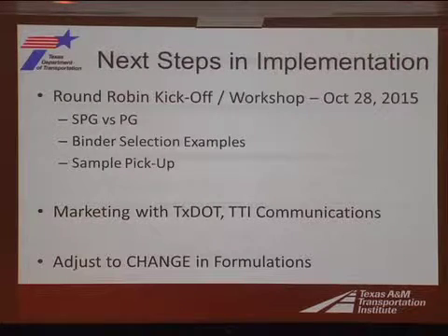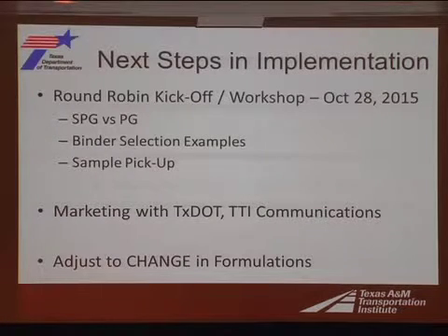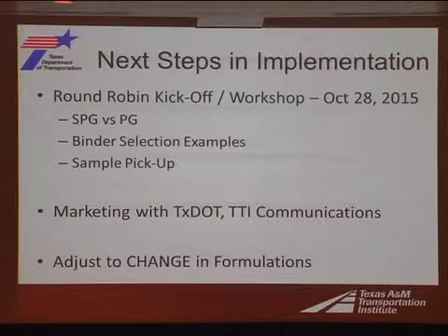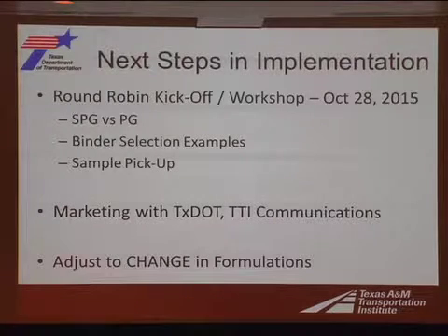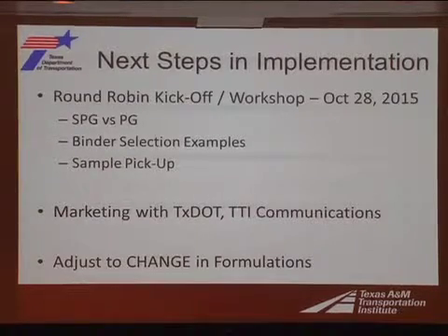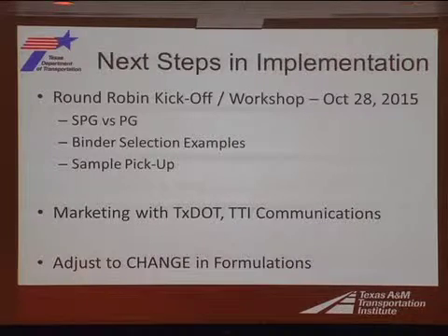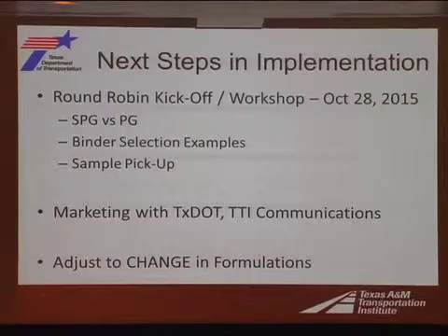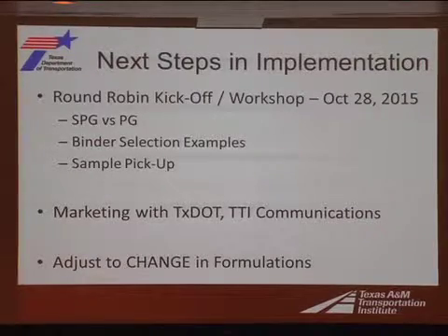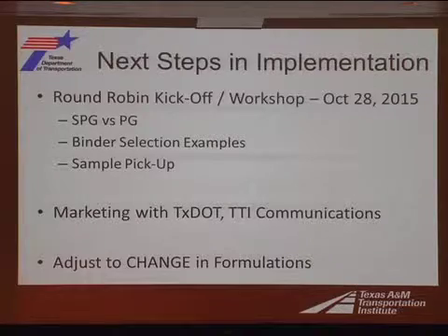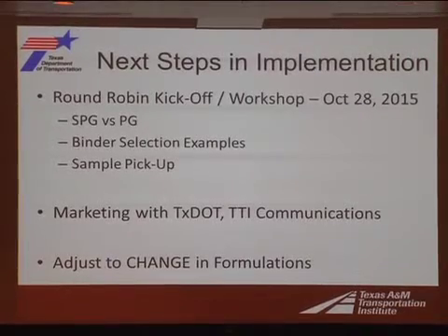We're still marketing stuff with TxDOT, and we're still out looking for trial projects. We're always ready for more trial projects. If there's a district that is not doing any SPG projects right now, contact me, contact Amy. We'll coordinate on that. And the thing to remember about that is you'll be using a different binder specification, but it doesn't change the way you build the seal coat. It just means that we'll need to get together and select the right grade of binder, and then you'll want to coordinate with TTI so they can get out there and collect data, collect samples, monitor the project, and that sort of thing. So it should be pretty easy to do those things.